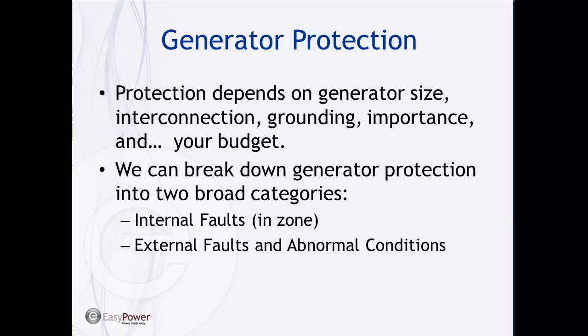So if you have a large generator in your system, that's a major investment. It's a long lead item, and so if you're going to have damage to the equipment or to the generator, you want to minimize that to the extent possible. And ideally, if you have a winding fault, you want to be able to just replace that winding and not have to restack the stator core due to a lot of damage to the core. So those are the goals.